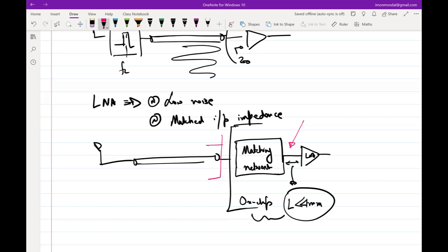There is no possibility of any destructive interference, or any other kind of signal interference with respect to the forward going and the reflected wave, other than constructive interference. Only constructive interference can happen if you have no delay between the forward and the echo, which essentially means that there is no echo. You can treat it as a lumped circuit, by R1 by R1 plus R2 directly, similar to that.